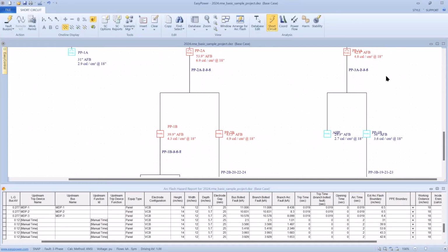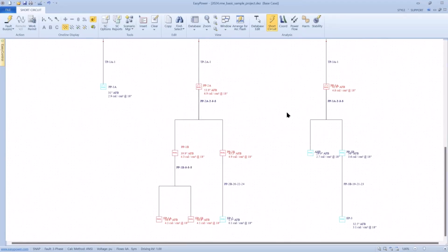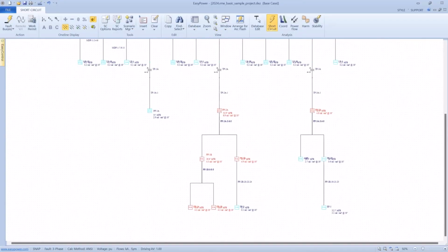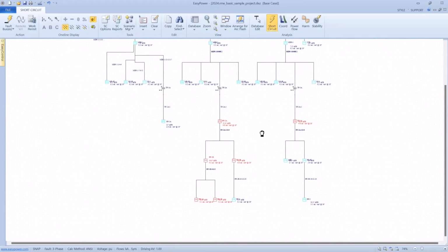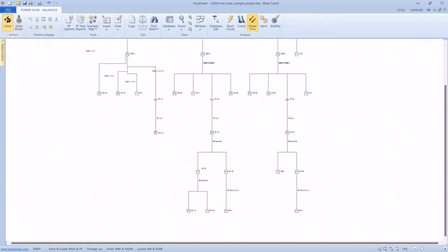Now, this is the extra added. When you look at the options menu, we recommend including Revit integration and PowerFlow as part of the basic arc flash combination pack, if you will. And because of that, I'm going to go to PowerFlow because it can catch overloading issues that may be the result of not adjusting the size properly on the cables. So now we go into PowerFlow, solve the equations,